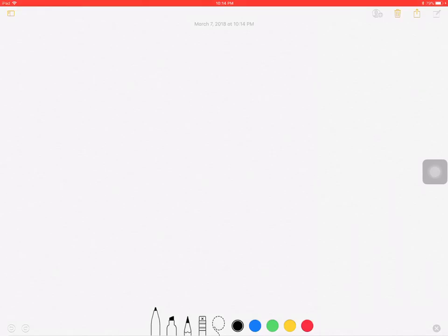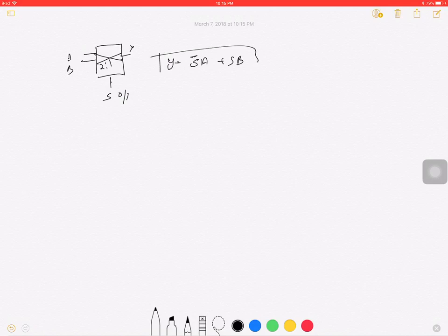In this video we are going to learn a Verilog program of 2:1 mux and understand how a mux works. So a mux has two inputs. Let's take a 2:1 mux. That's A, B, Y. So if S is 0, the first line is connected. If S is 1, this is connected. It's that simple, right? So let us write the Boolean expression for this. If S is 0, that is S bar, A is selected. If S is 1, B is selected.